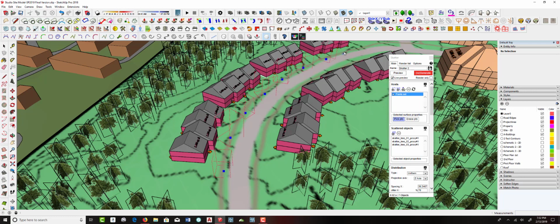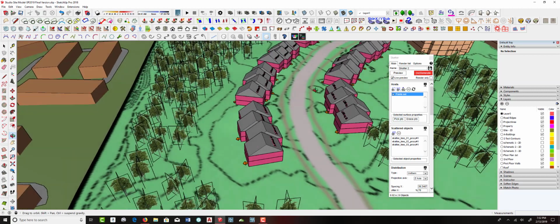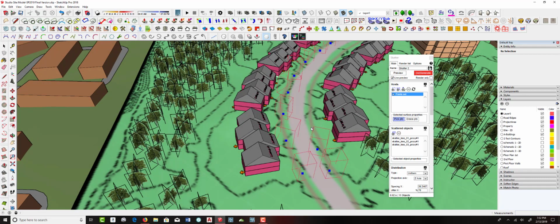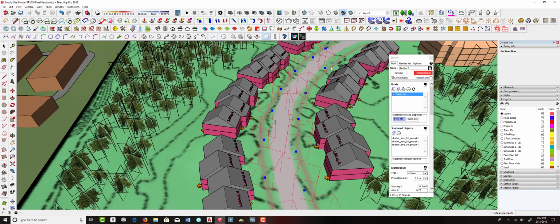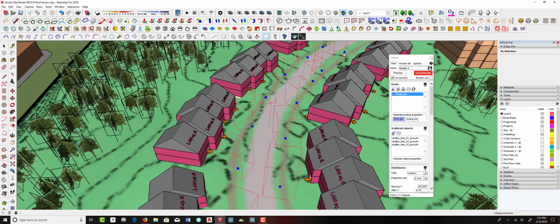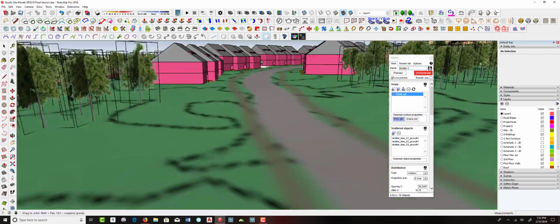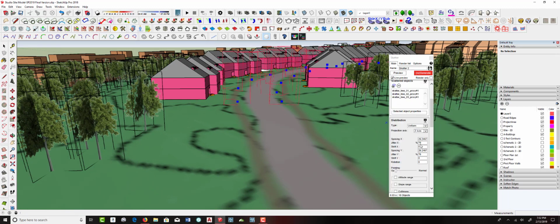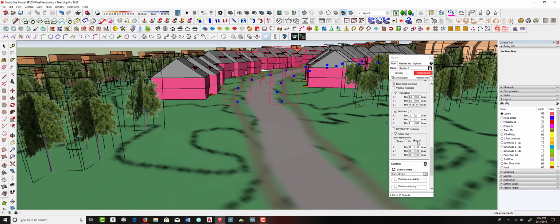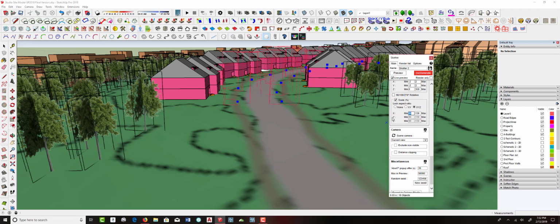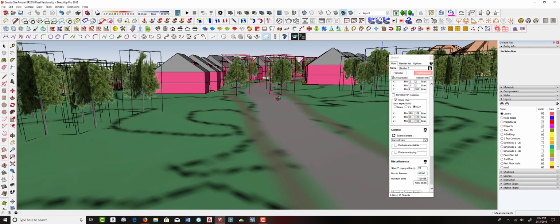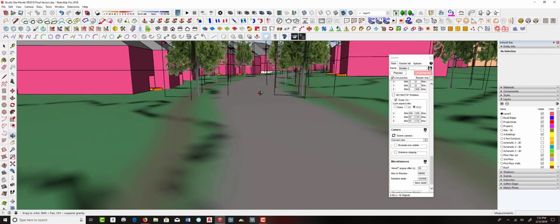And if I had a line, I could actually use a line to do that. But again, since this is an image, a bitmap here, I don't really have the geometry, and that's okay. I'm just going to come in here and place these wherever I want. And you can also notice in this case, they're kind of coming in random sizes, and probably for street trees, you might not want it that varied. So in this case, I will go down and say, I want these about the same. So 100, 100, regenerate. So now it's kind of placing those street trees in there.